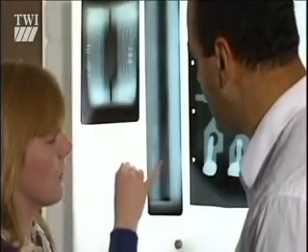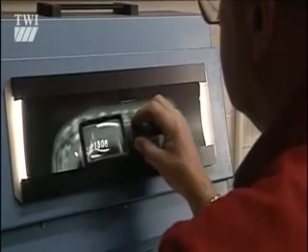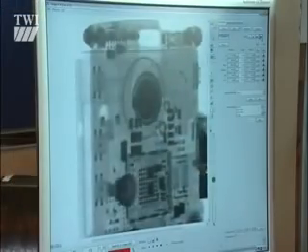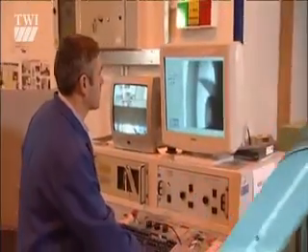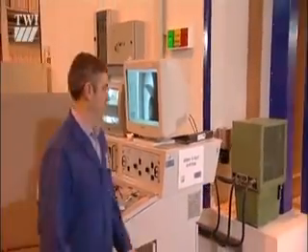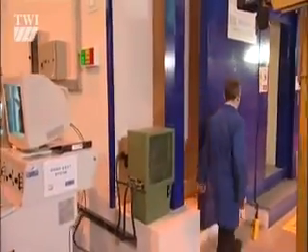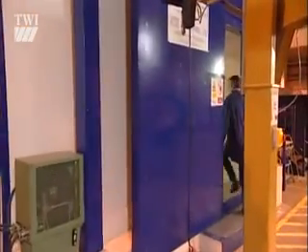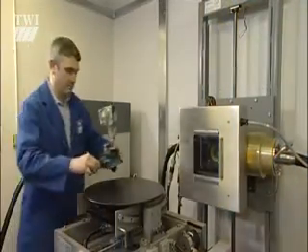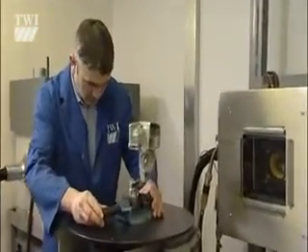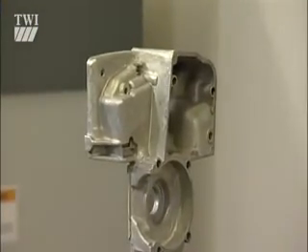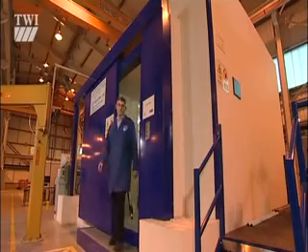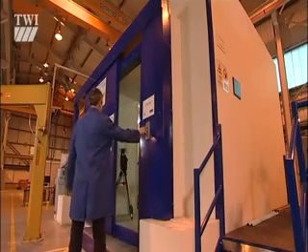In recent years, wet radiography, which uses photographic films and traditional darkroom technology, has been overtaken by digital radiography. Now, digital radiography relies on the ability of certain substances to fluoresce when they are exposed to X radiation. The fluorescence that's emitted from the substance is made to create an analog electronic signal, which can be converted to a digital signal by means of an analog to digital converter.